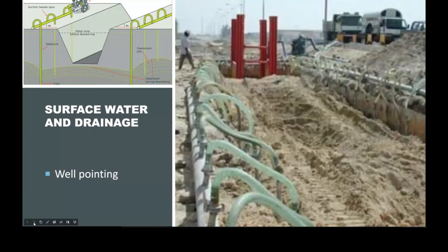Another factor that can cause trench collapse is water flowing into a trench or a high water table, which might mean you can't even do the job in the first place. In some cases, like they're doing some stormwater main replacements in Jackson Street and around there going out to the beach, the water table is so high when the tide's in, it's only maybe 1 meter deep. So when you dig deeper than 1 meter, it fills up with water pretty much straight away, which makes it very hard to do your job.